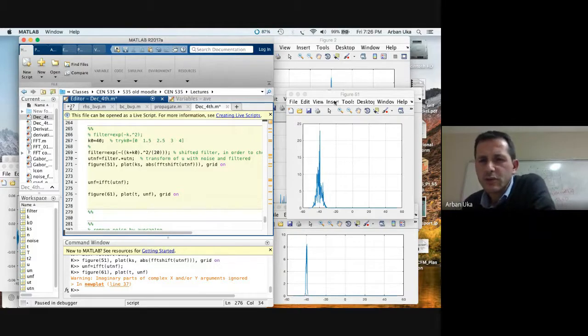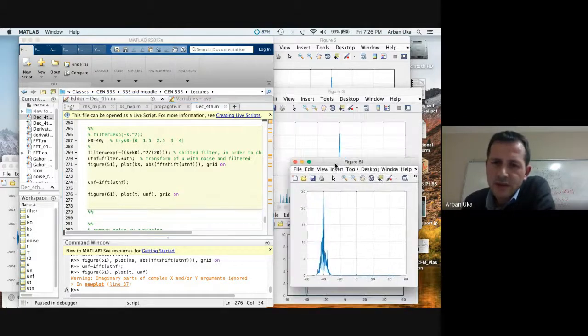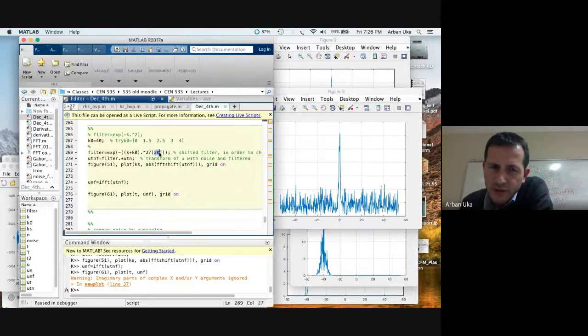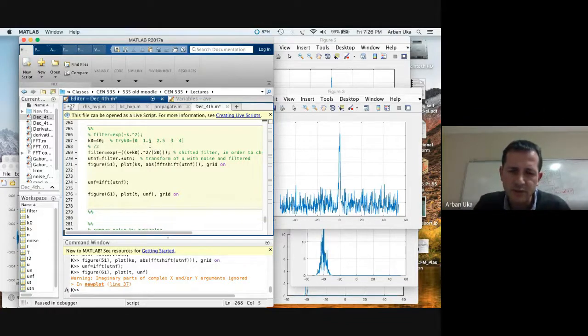In order to have the filter centered at 40, and also preserve some of the lowest frequency, the sigma of this filter should be 20 plus 20, 40. So this is 40. Actually, here, when you set this 20, this 20 is equal, because we divide by 2 times sigma times sigma.